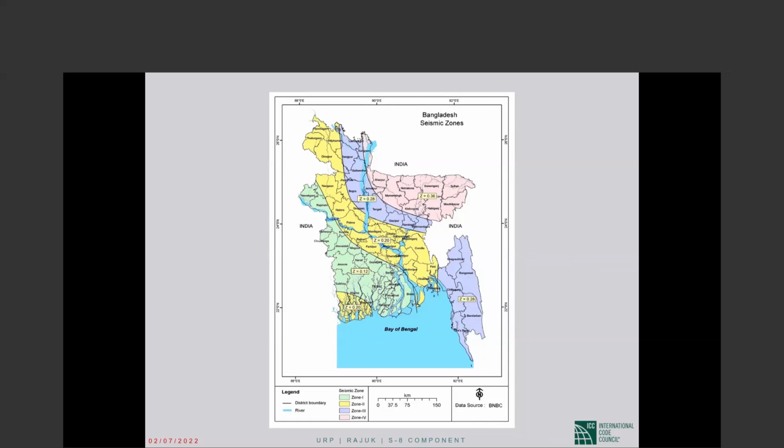And when the infill is lost, the stiffness of the building drops pretty drastically. Obviously, not all the infill is lost at one time, but even then, in a significant earthquake, the stiffness will go down significantly, and then the building has a different period.